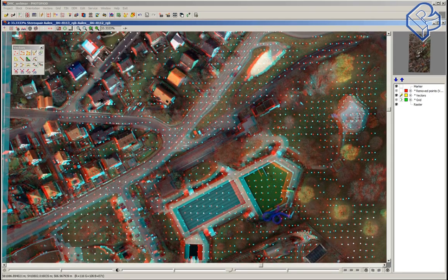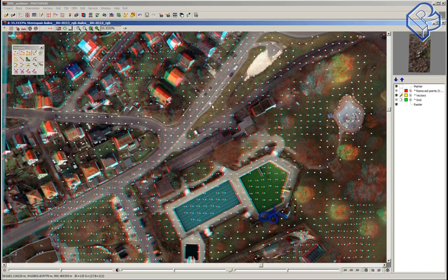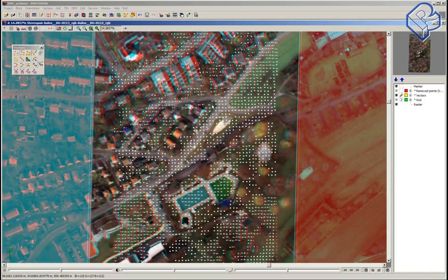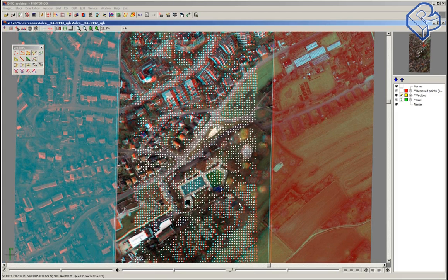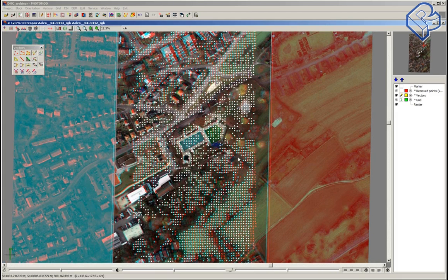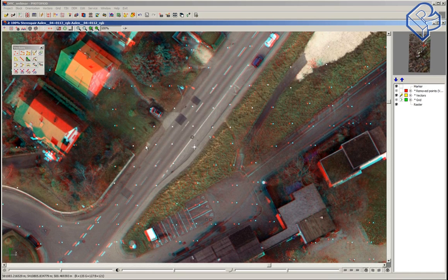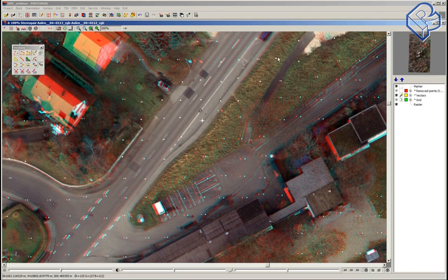Okay, after we finished with 3D points, we can define this model with break lines. For example, just activate this layer here, use one by one zoom, and for example here, let's create some break lines. In order to do this, we can create a new layer, of course, and use the same layer.